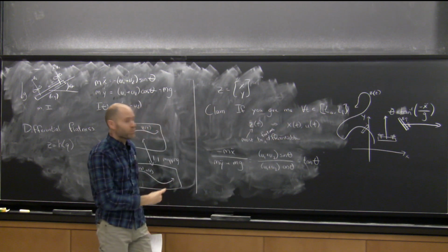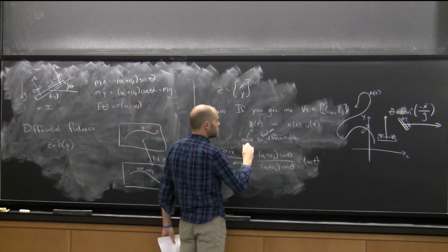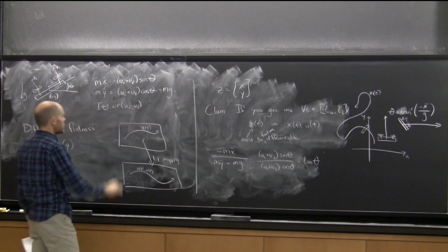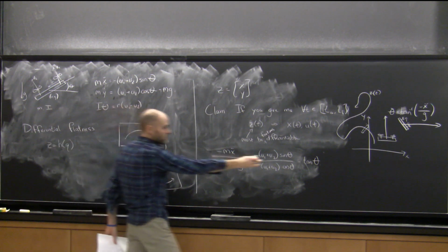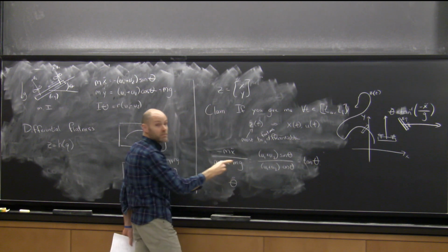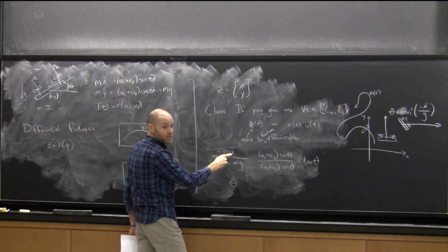Furthermore, the control inputs are completely specified. In order for this to satisfy all the equations of motion, an easy way to see that is I could differentiate. Once I have this relationship, I can differentiate this twice to get what theta double dot has to be. That's where the fourth order thing comes in.